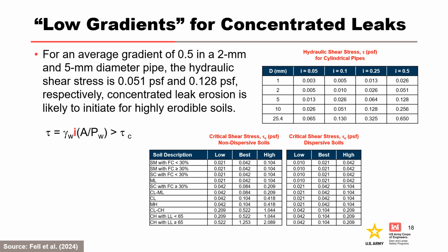You cannot just discuss gradient for concentrated leak erosion. Hydraulic shear stress is the parameter that drives initiation. It is a function of hydraulic gradient as well as pipe or crack geometry, and the critical shear stress is dependent on erodibility. The top table illustrates how the hydraulic shear stress increases with both increasing hydraulic gradient and pipe diameter for cylindrical pipe. The hydraulic shear stress is then compared to the critical values in the bottom table.